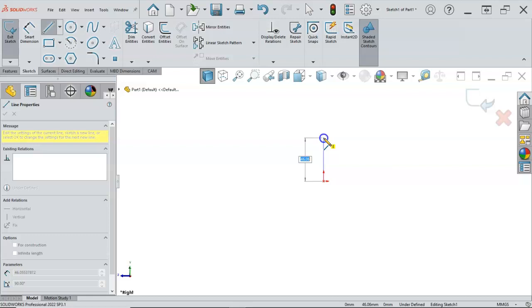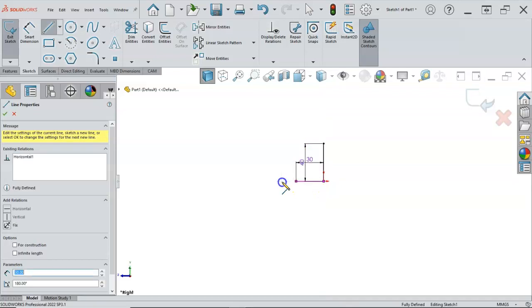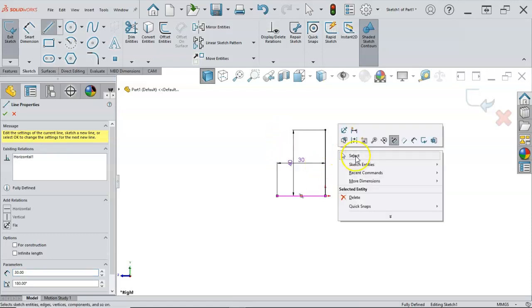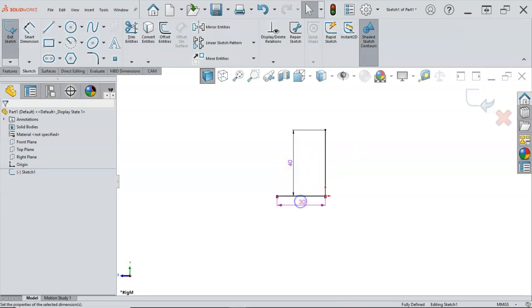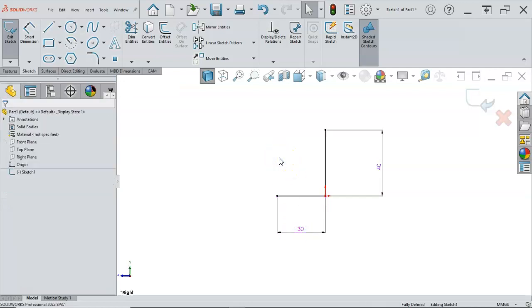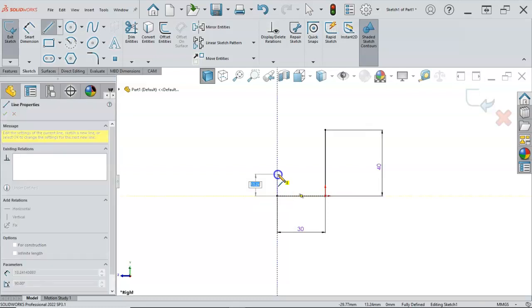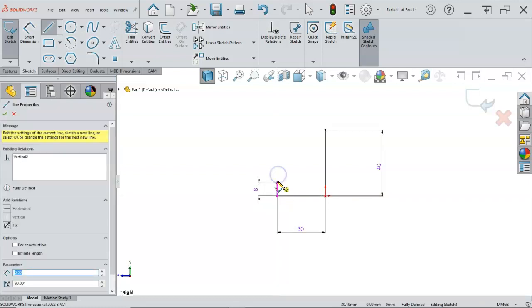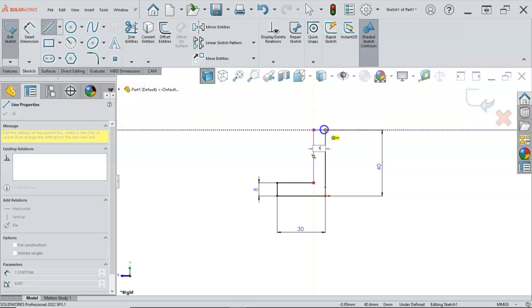So for the height, I think I decided it was 40. So if I use the sketch numeric input, and then we do have a dimension for the 30. And those are kind of where I want to sketch. So if I right click, I'll do the select and I'll just get those out of my way. All right, so it kind of put those in place. So if I hit L on the keyboard, that'll drop me into the line. This side is 8, and we'll bring it back and up. And when I bring it over, then I can put in the 10.